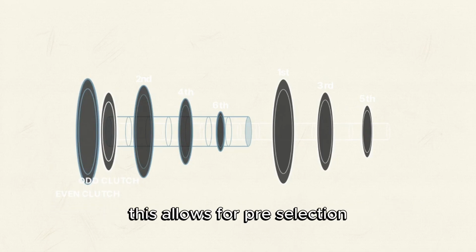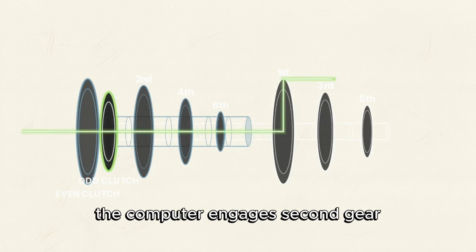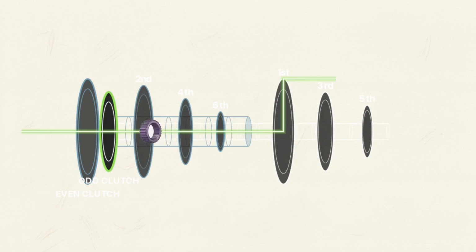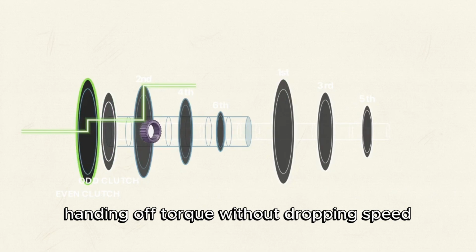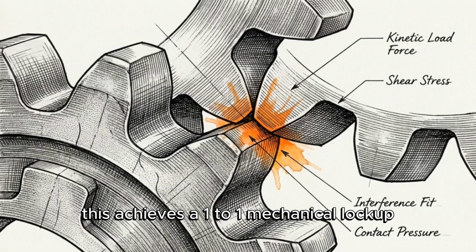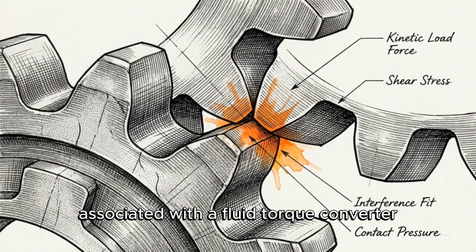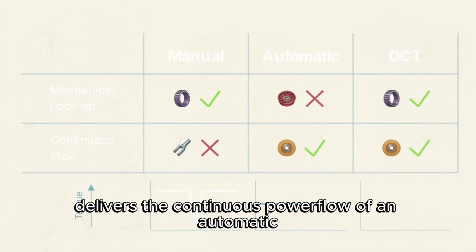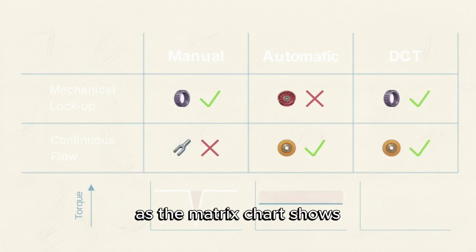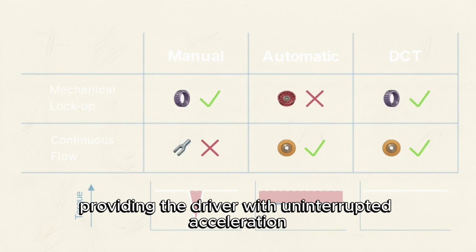This allows for pre-selection. While accelerating in first gear, the computer engages second gear on the freewheeling outer shaft. The shift takes 8 milliseconds. The odd clutch releases, the even clutch clamps down, handing off torque without dropping speed. This achieves a 1-to-1 mechanical lockup, removing the parasitic loss associated with a fluid torque converter. It simultaneously delivers the continuous power flow of an automatic. As the matrix chart shows, the torque delivery remains flat, providing the driver with uninterrupted acceleration.